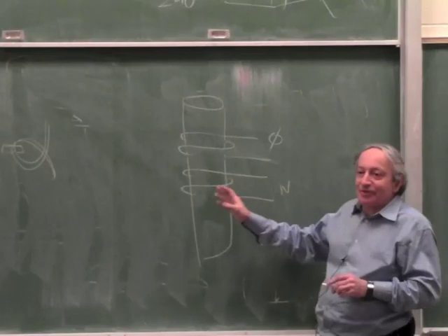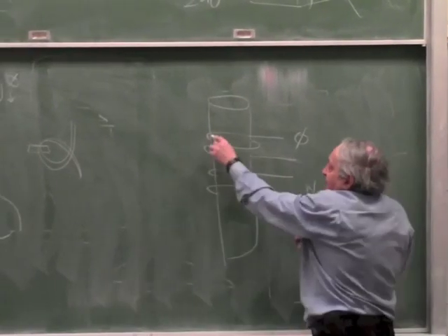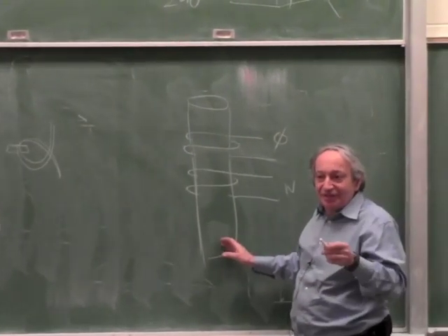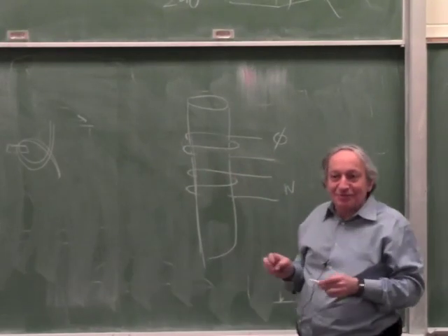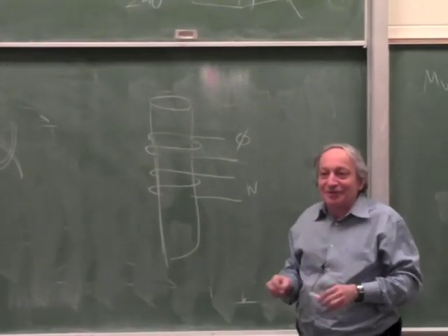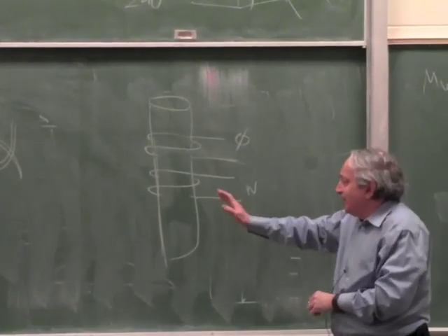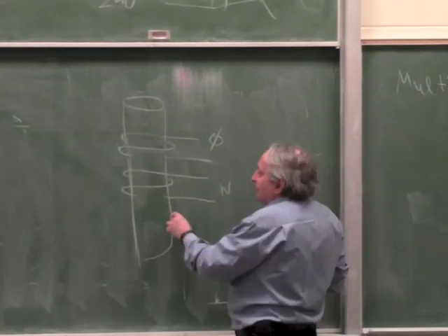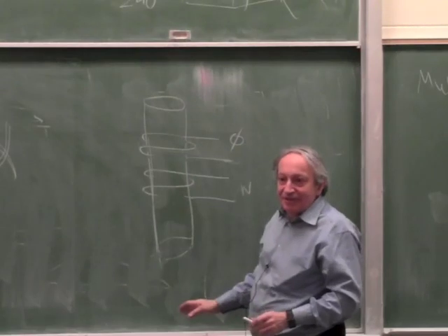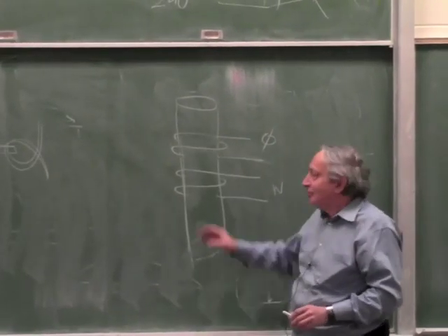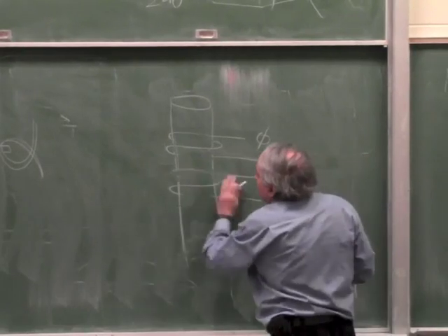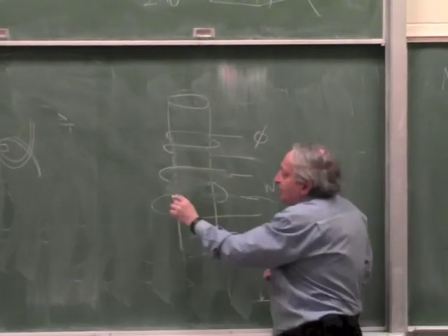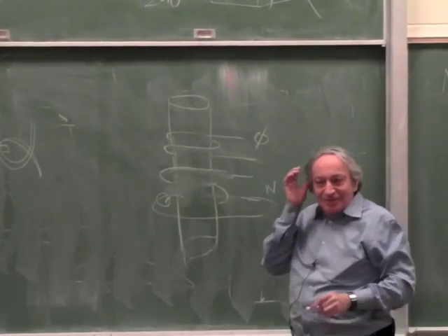Just because of a nice property of magnetic fields, that if you have a piece of steel inside, it will channel all the fields of the steel, just like the explanation why in an LVDT it doesn't matter laterally. And that's what makes it work so well. So you don't have to do it carefully at all. In terms of radiating some field outside, it's important to put the wires close together. But in terms of magnetic field, if you have a piece of high permeability, this magnetic field is not affected at all by the way it's wound. Even if one winding is much bigger, it has very little effect. There is some leakage field which escapes, but it doesn't have to be that carefully wound.